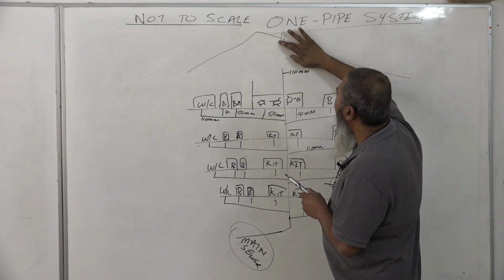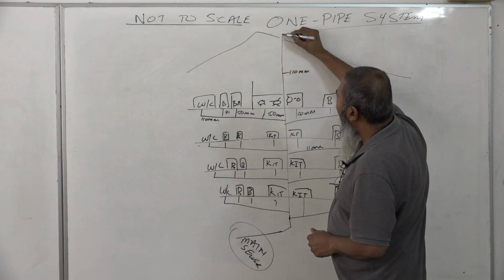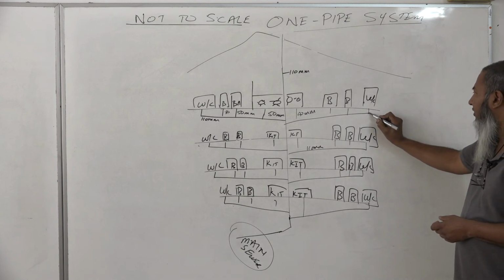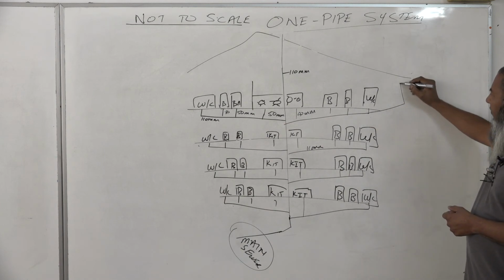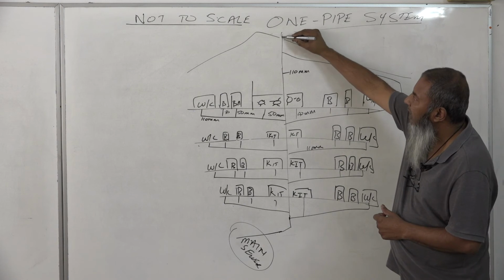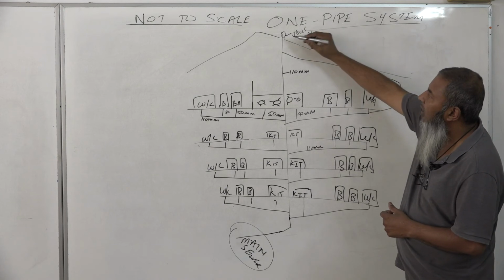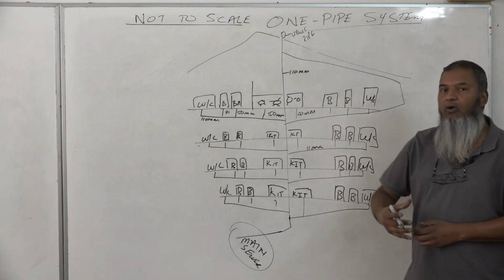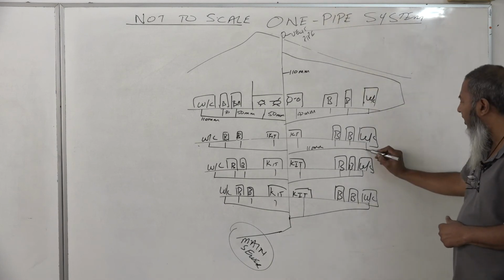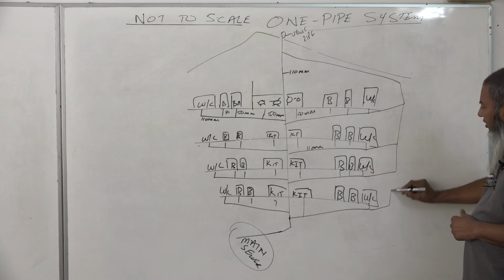Okay, let's just restructure that, people, so we don't confuse ourselves. That's the roof. Okay. So commonly what happens here is we join a pipe at an angle going up to the 110 mm vent pipe. This becomes the vent pipe. Why? Because this pipe is open on the roof, allowing all the fumes to escape from there. Simple structure. The same thing would happen to the next one. It comes up, it will join here. It will come up again, it will join there. Come up again, it will join.